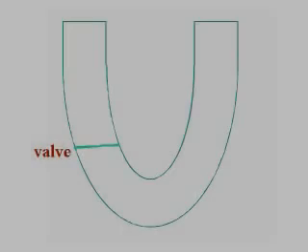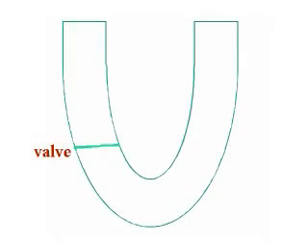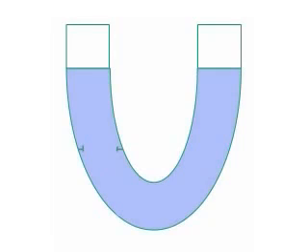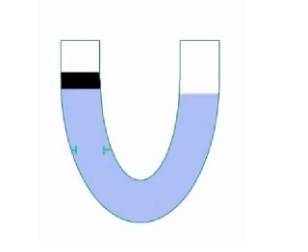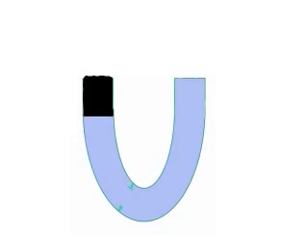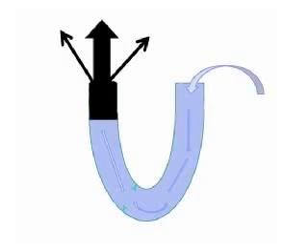With simple salt water, it will make it almost to the surface. Let's go back to our U-tube. Again, with only water, what will happen if I keep adding water from one side with the valve open? Both sides would fill to the top, and then it would spill out on the left-hand side. Now remember what happened when I added oil. The level of the fluid on the side with the oil rose higher. Now, if I keep adding water, the side with the oil will gush up and out before it overflows.